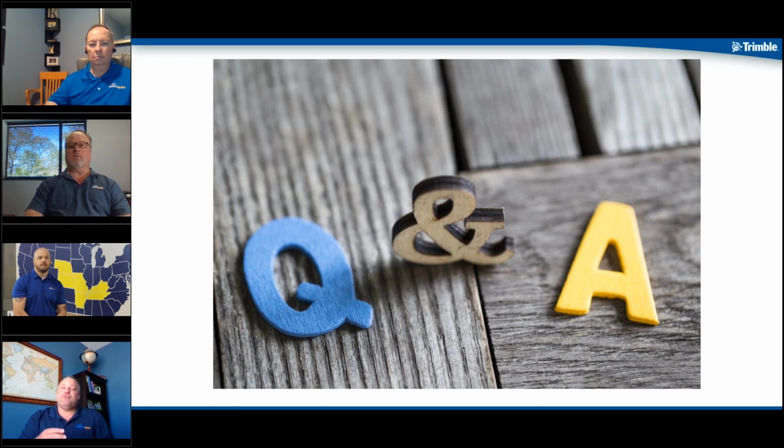Step two is usually shoot your control points as soon as you get done setting up. Don't wait till the end of the day. You've been set up for 3 or 4 hours and you haven't checked anything. You've just been doing layout and you're like, oh, I need to shoot a bunch of control points. Shoot your control points right away. Make sure your temperature and pressure are set properly.